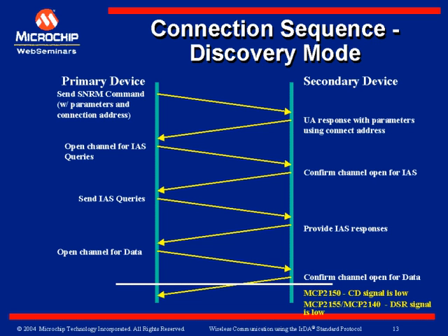At this point it is now the responsibility of the primary device to send an open channel for data. On a PC, this really only occurs after a PC program has attached to the IR port. So for example, if you just have your IR port enabled on a PC and you bring a secondary device in range, you will see on the system tray a little IR icon, if appropriately configured, come up and indicate that a device has been located. But a link will not be established unless a PC program actually opens and connects to that IR port so data can be communicated across.